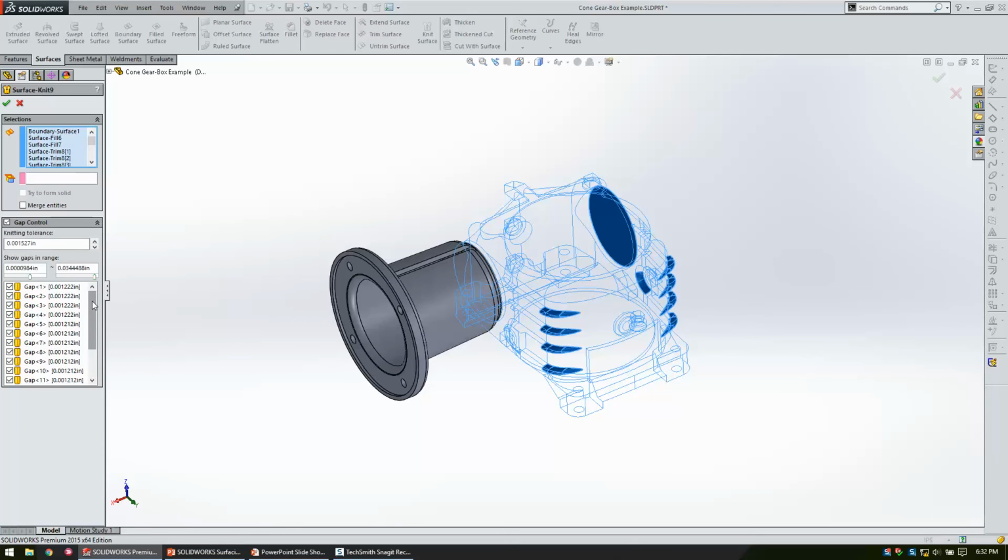Thanks for bringing that up. In SolidWorks 2013, 14, 2012, something around that era, they introduced this gap control command, which basically analyzes the model, finds surface edges that are so far apart, and says, hey, do you just want to close this gap? The old knit command, I think, did it automatically to a limited degree, but that gap tolerance was fixed, and you didn't really have control or visibility over it. So now they let you see it, and then they let you control it.